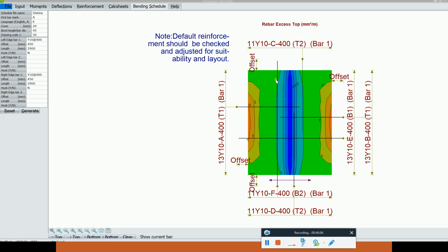Now, the line which is cutting the slab fully is representing the bottom reinforcement, because we supply the bottom reinforcement on the entire slab, while the top is not going to be the same. So the first thing we need to do is check the line which is cutting the slab fully. So we have one here, and then we have another one here.